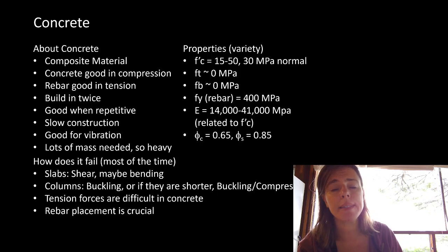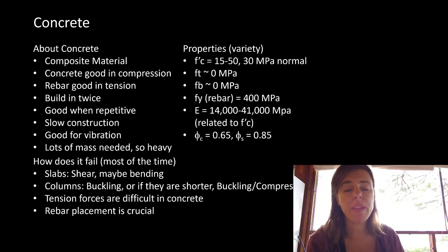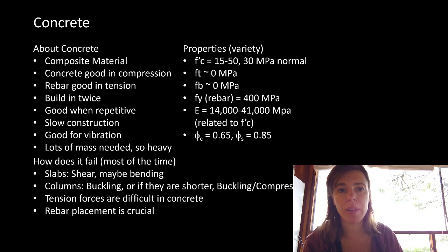We have to build it twice. The problem with concrete is we need wood formwork to hold this thing in place because it's liquid, and we literally pour our building into place, and it isn't able to even hold up its own self-weight until it's cured. So we need something to hold it up while it's curing. So we have to build a wood building to hold up a concrete building.